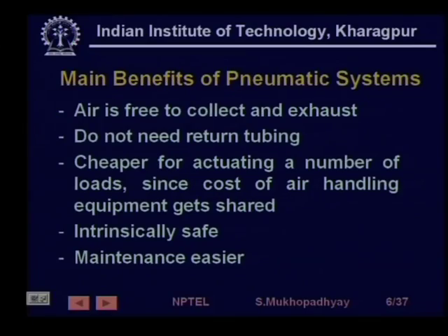Another important advantage of pneumatic systems is that while electric systems are prone to fire because of electric sparks, and hydraulic oil is inflammable, being a petroleum derivative, pneumatic systems are intrinsically safe and therefore often preferred in places like explosive environments. Let's say a natural gas plant would have a lot of applications for pneumatic control systems to be free from the hazard of explosion.